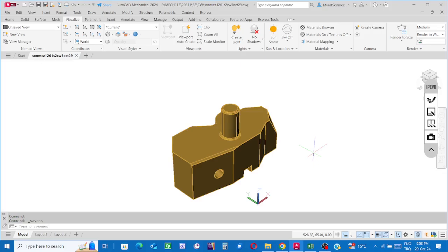Directly start the 3D polyline creation process and then be able to write the coordinates of the corner points relative to the preceding one. For the first point, the preceding point is the origin. Can directly write the given coordinate values, but for the second and the third points, be able to write the relative coordinate relative to the preceding point.